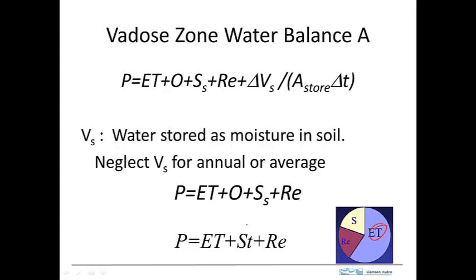But in any case, there would be a higher fraction of recharge than storm flow. So let's say for the purposes of example that the fraction of ET stays the same. But if we have this area underlain by dune sand, then we might expect that there would be a big fraction of recharge and a small fraction here of storm flow. Okay, so the geology is going to play a big role in how the pie is distributed, basically how the rainfall is distributed.